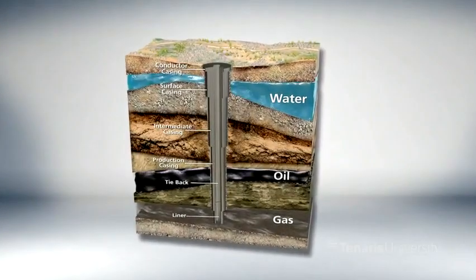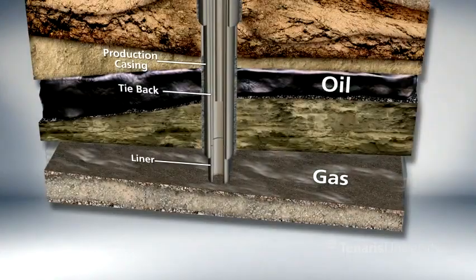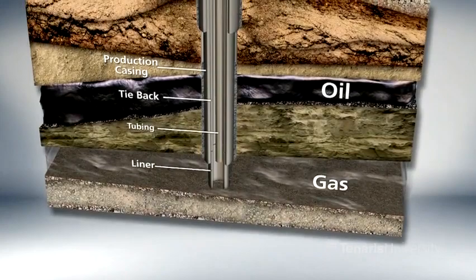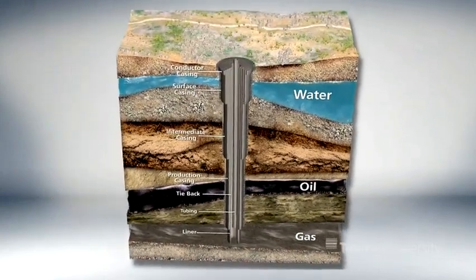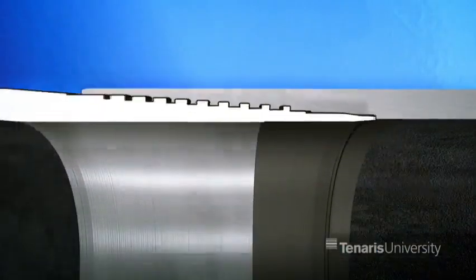Well, at this point we have already drilled and cased our well, and it will keep the integrity during its entire life. Now we have to put it into production, and how can we do that? Just running the very last string, which is the tubing. All the pipes used either as casing or tubing are comprised of two different parts, the pipe body itself and the connections. And the standard way to identify them is through their dimension and mass characteristics, the steel grade, and the connection. Let's see this with an example.